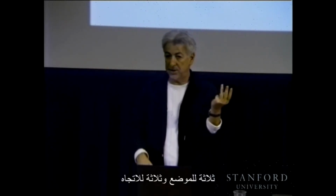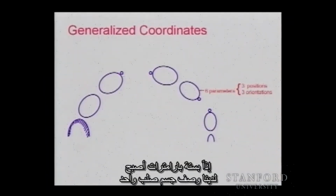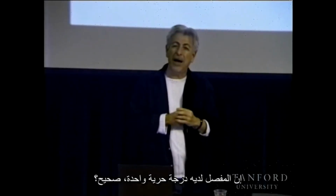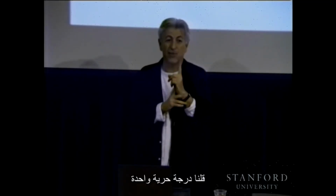6. 3 for the position and 3 for the orientation. So with 6 parameters, we have a description of one rigid body. Now we have n moving rigid bodies. In total, we need 6n. Now, let's think about those constraints introduced by the joints. If we put back the joints, we are going to introduce constraints. Now, a joint has 1 degree of freedom, right? We said 1 degree of freedom.